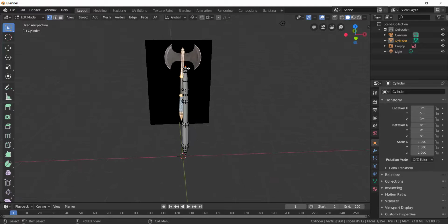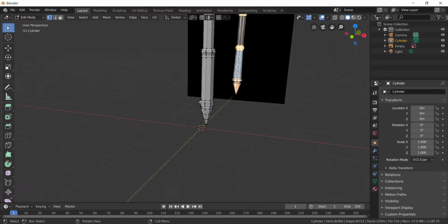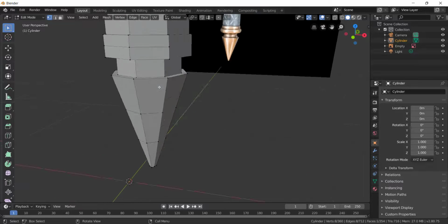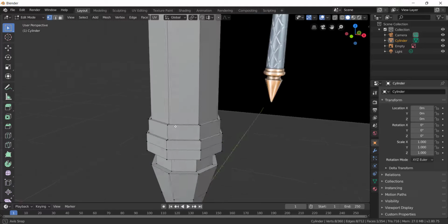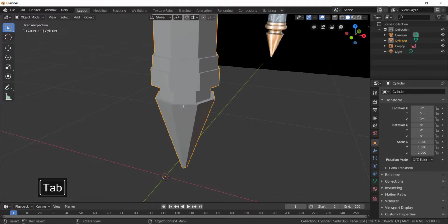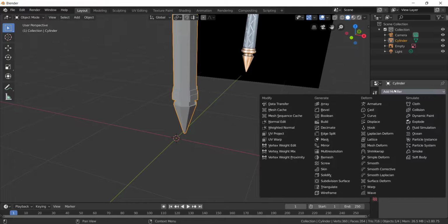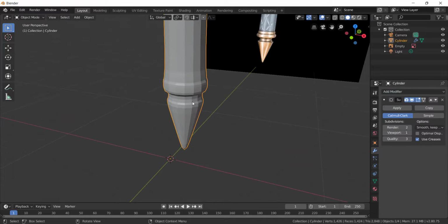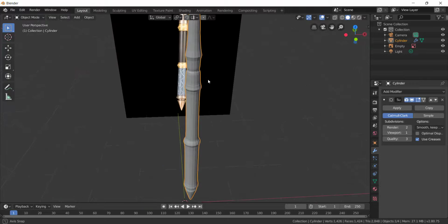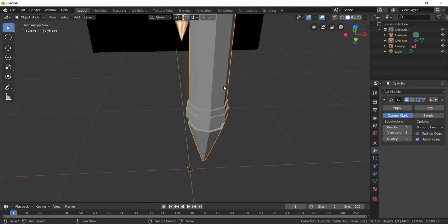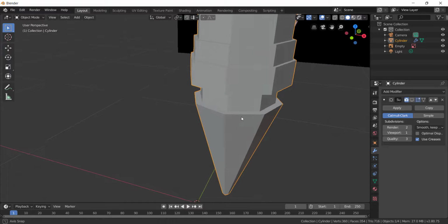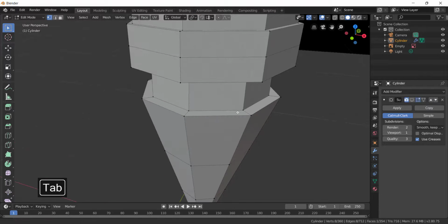We have created the shape, we need to do a lot, so that I will tell you now. We have created the shape, but we didn't give the smoothness, bevel, and also we will do that. Okay, see why we should do that: if I add a subdivision smoothness, see, all became very smooth, the shape is gone. So to preserve the shape, we need to preserve the edges. To preserve the edges, you need to bevel, or you need to create supporting edges. Simply, I will use bevel.